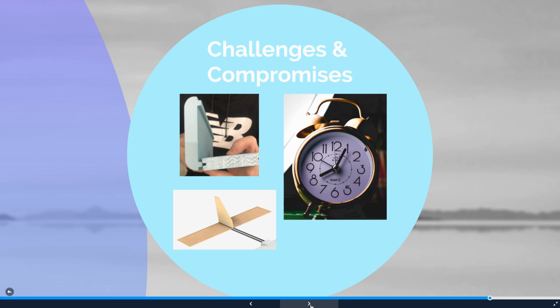This project allowed us to understand some of the challenges that come with designing and building a UAV. Often several issues incurred due to our lack of experience caused changes in the UAV design, such as including a door in the fuselage roof to allow access to the payload and electronics, and incorporating 2 rods for the tail to reduce the twisting motion. However, one of the major challenges was time management, as there was a time constraint on getting parts from the laser cutting and hot wiring machines, so building each iteration of the design took much longer than initially predicted.